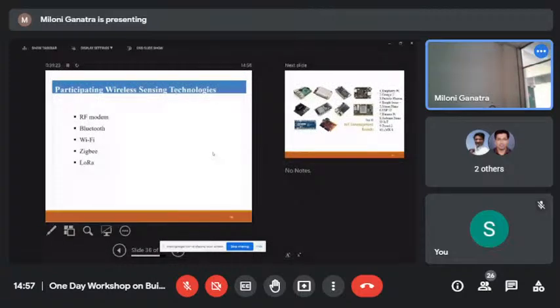No 4G, 5G, nothing. No internet, nothing. It is modules at the transmitter and at the receiver, and it can go a long distance. Again, you can also transmit video and audio. It's not that you cannot, but it will not go that long distance. So it is a trade-off: power, bandwidth, all these things.